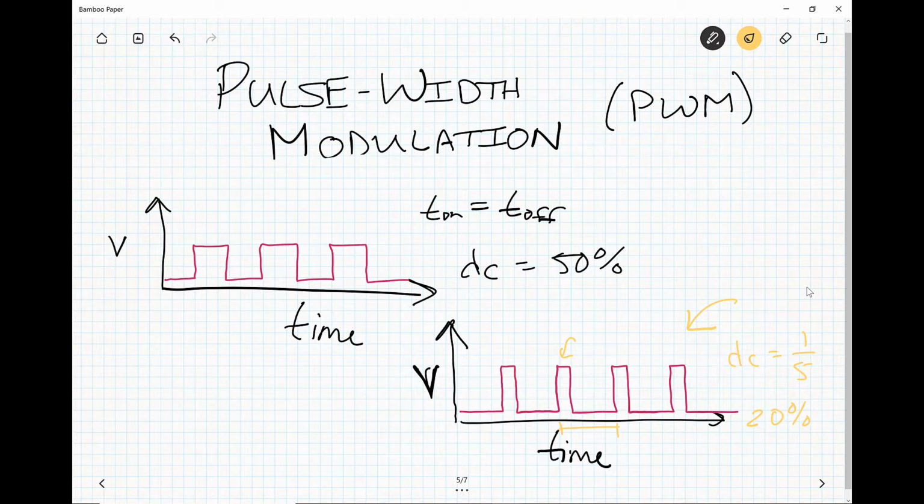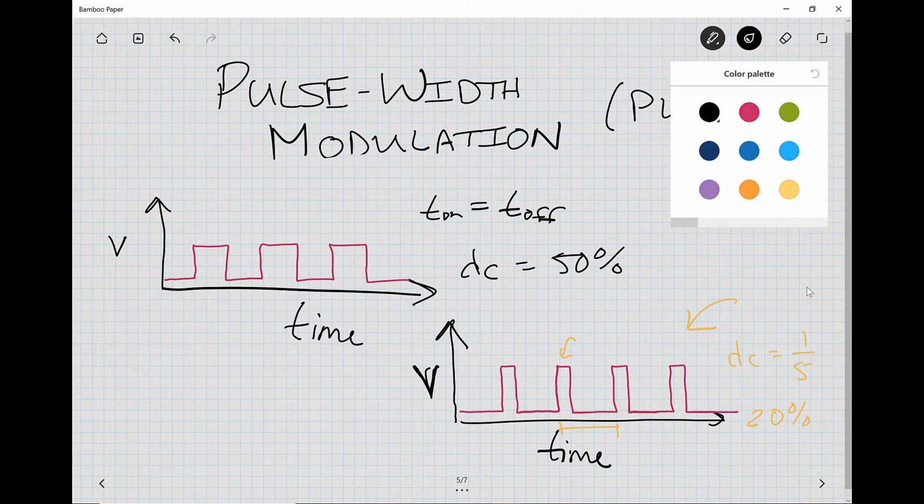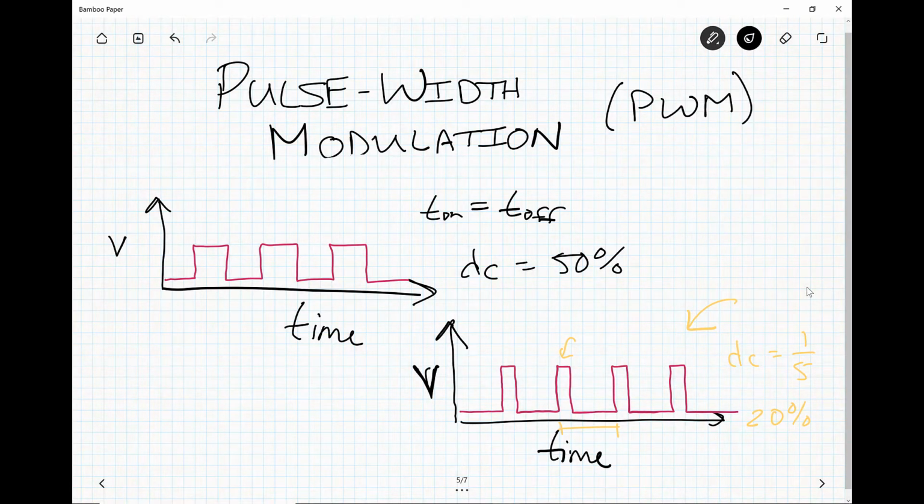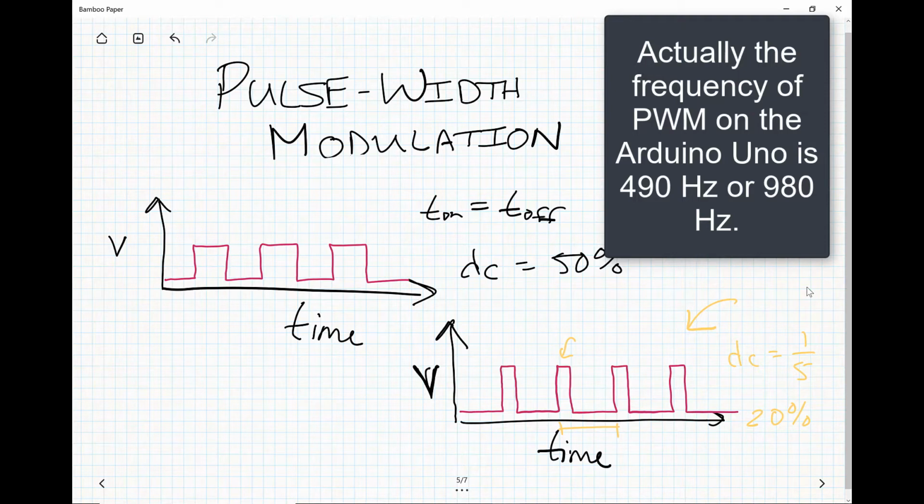All right, so how does all of this allow us to simulate analog signals? Well, a bit that I left out here is that these oscillations are carried out very quickly, on the order of 1,000 times a second or more. And so in many circuits, for all intents and purposes, the circuit is essentially not seeing high and low, high and low.